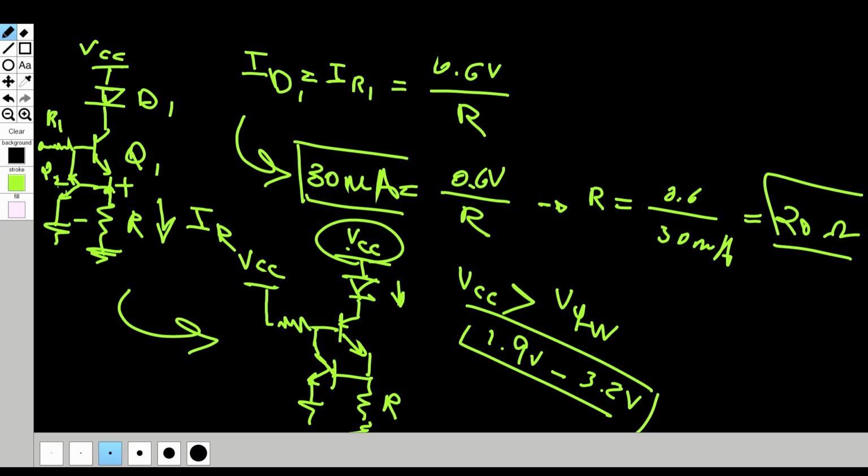But we're going to do some power calculations later on. But for a back of a napkin calculation, that's all you need. You just need an LED, two simple NPN transistors and a resistor. And then now you have a constant current LED driver, where it'll make sure that there will be a constant brightness no matter what the input voltage is, what the VCC is.